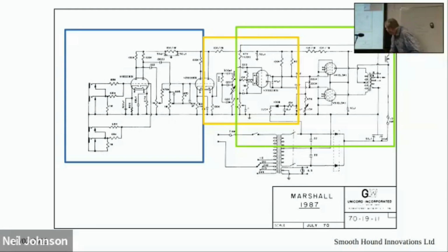As I said just now, I happen to know that this driver here is a cathode follower. I happen to know that you can't overdrive that gate, so there's no need to include that one. So we have a pre part of the circuit, which is simulated in one block. We have a mid part of the circuit, which includes the tone stack and the phase splitter here, because this cathode follower can overdrive the gates of this phase splitter.